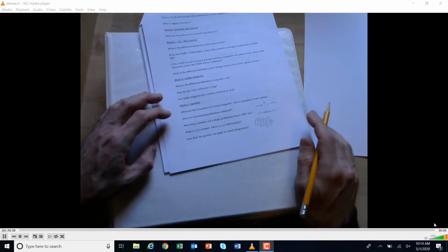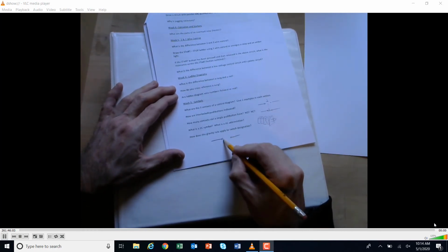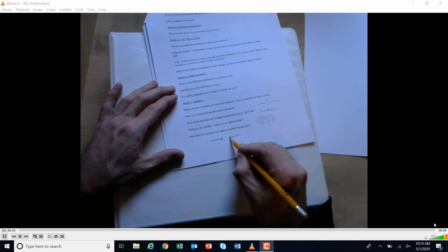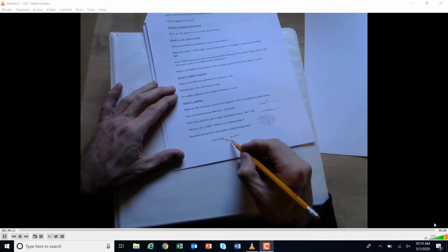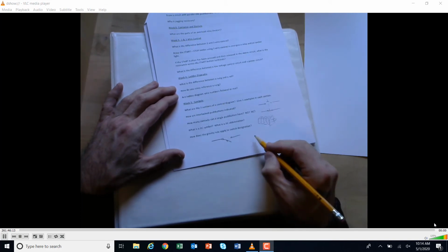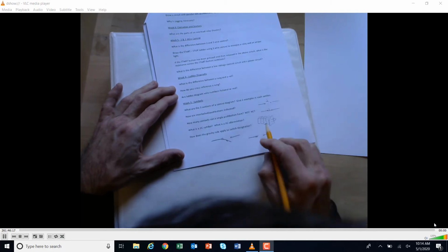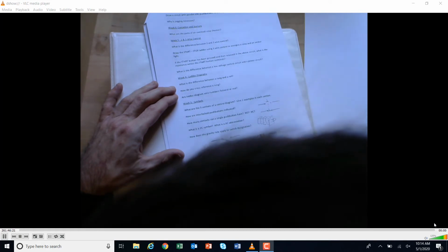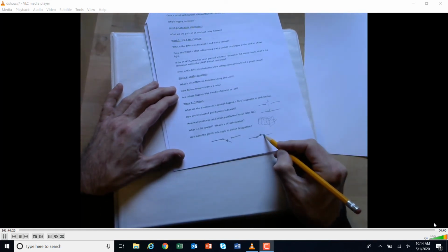How does the gravity rule apply to switch designation? Well, remember, you kind of say, if there was a switch below this catch here, what would it do? Well, it would fall open. Okay, that's a limit switch. It would fall open, and that would be the normally open case. Whereas if you had a switch that was up here, what would happen? Well, it would fall until it hit that right there, and that would be a normally closed limit switch.